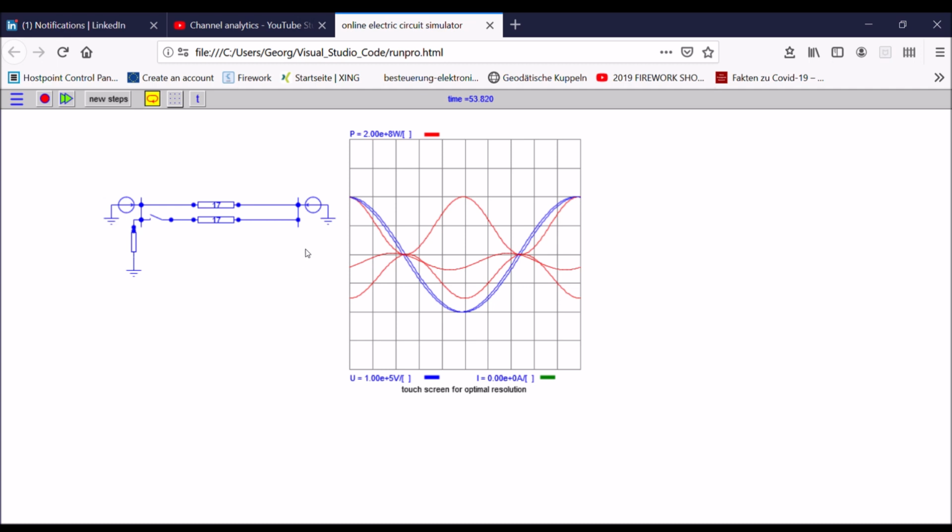I would have to increase the phase angle. When it was closed, it was around about 7 degrees to share. You see 7 degrees. And if I open it and still want to have the same sharing of the power, I would have to increase it from 7 to around about 10 degrees. Very sensitive with this relatively short line.